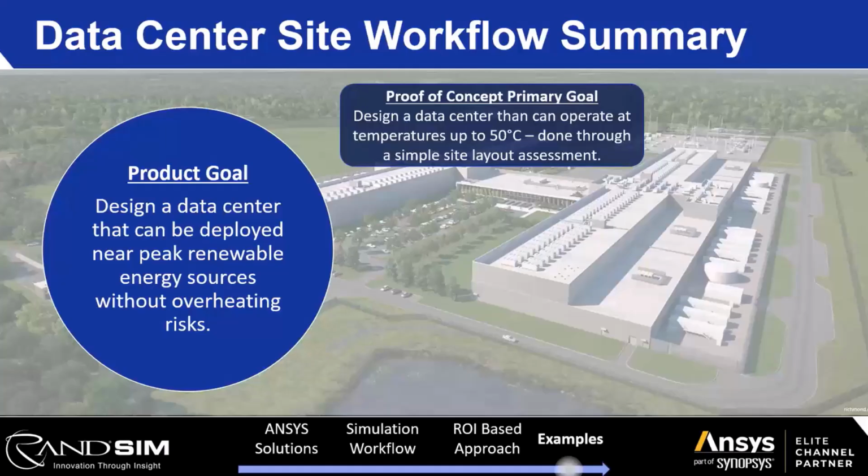When in reality, every chiller on a data center site re-ingests hot air, right? These things generate heat islands. They have a lot of hot air that is generated, and as a consequence, these sites are above ambient temperature flat out. That is how it works with these massive sites when you're dissipating that much thermal energy locally. And as a consequence of doing these preliminary concepts, you might be able to quickly